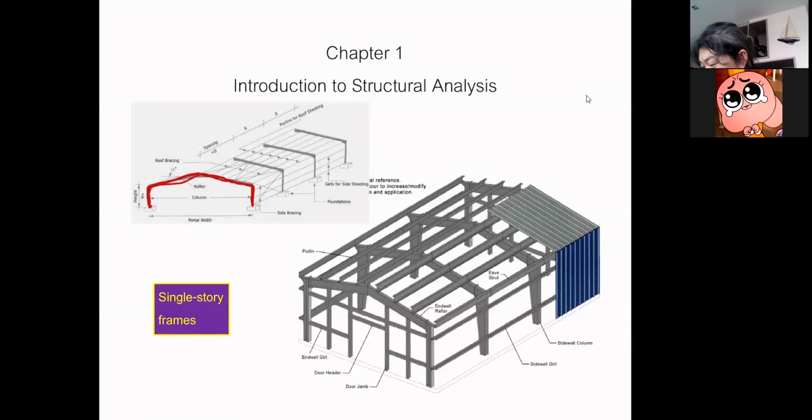And when you have a part of a wall like this one, the area becomes closed. That means this area can take the wind, right? So when the wind hits the area, this will be the area that is the responsibility of this frame. You can see that. So the wind on this blue area, wind can hit this, right?